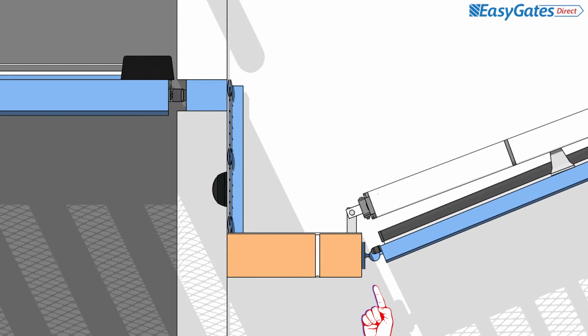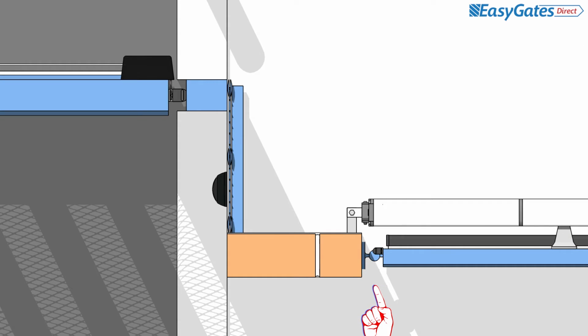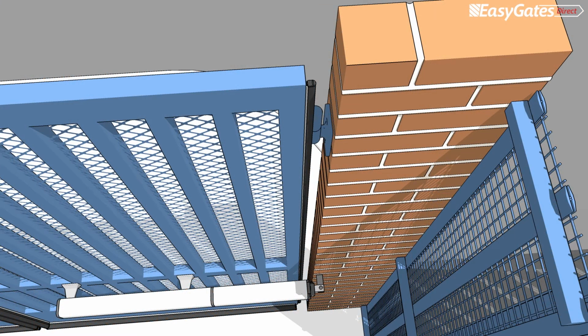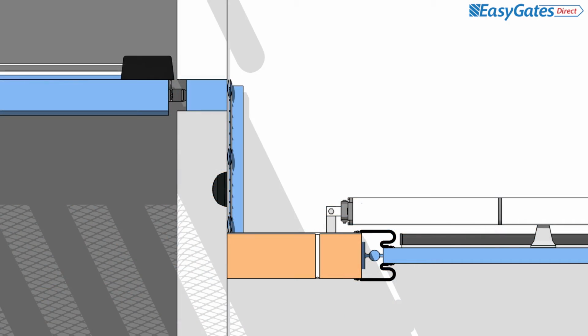When implementing this type of solution, the forces exerted by the gate cannot be easily or safely measured with current test equipment. The functionality of these edges should be tested periodically as recommended in the Code of Practice, and they should be connected to the gate control system and monitored as part of the Code of Practice requirements.